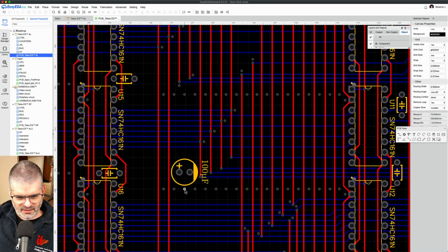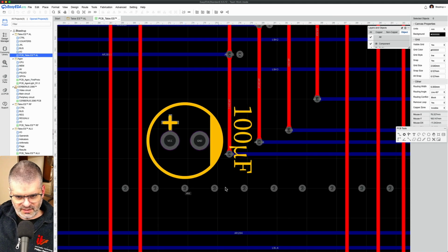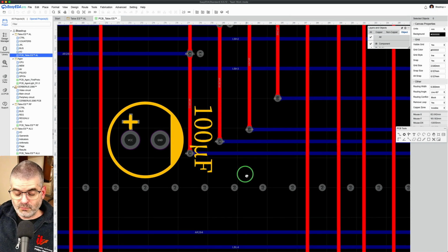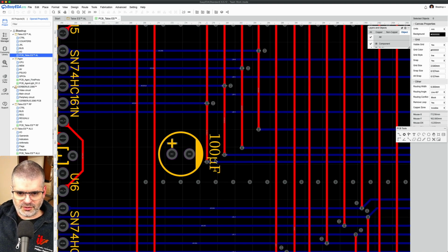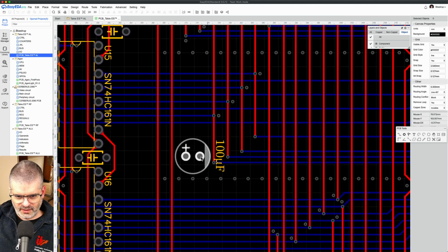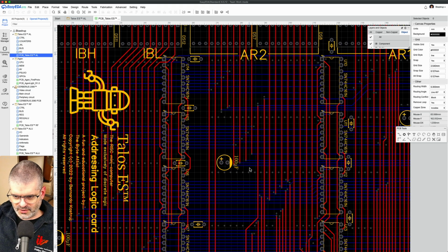But it's okay. These are VCC vias, right? Yeah, they will not work as return path vias, but they will work as transfer vias. That's not a problem. So this is not too bad. And there is a big ground pin right here. So the return path for these signals will probably spread and come to this ground pin and will not spread any further. It will end here. And it's a capacitor, which is even better. It's more helpful. It will provide the electrons for the return path. So this should be okay.